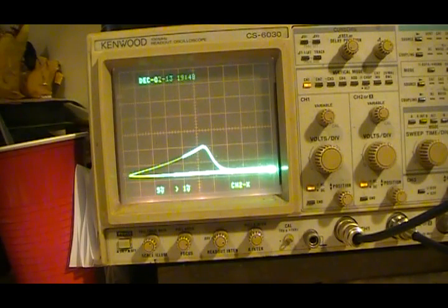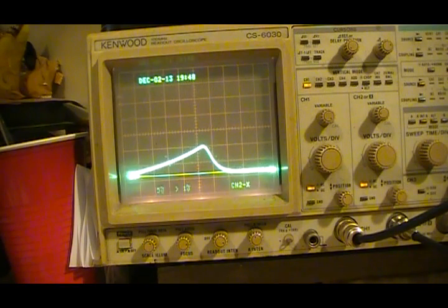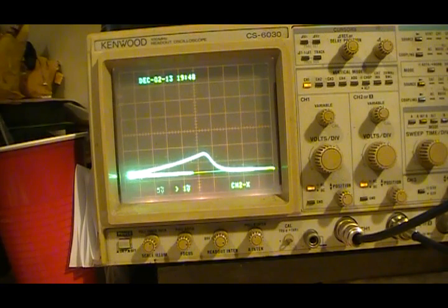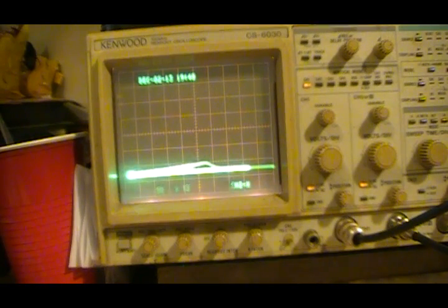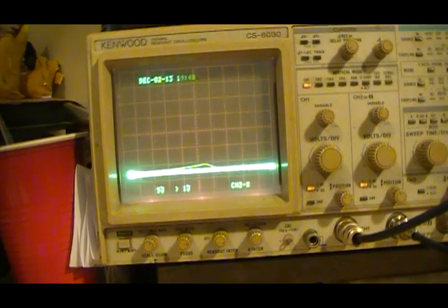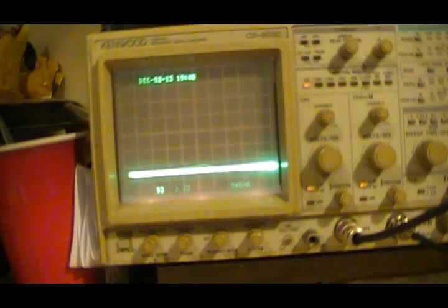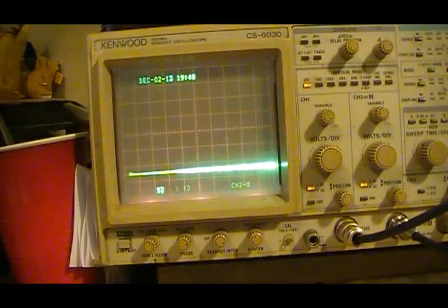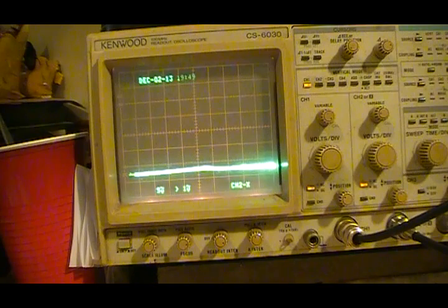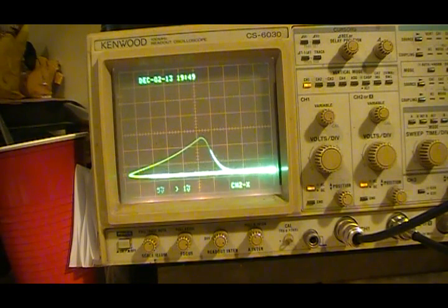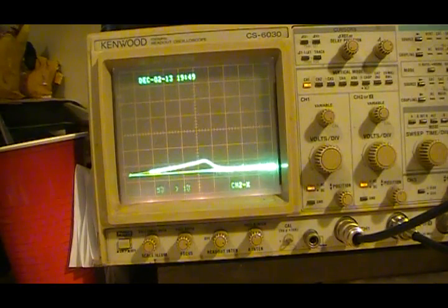There we go. Kind of lost a little bit of the blip here because I adjusted the generator up a little bit. But it's still giving me some troubles. Almost as though I think I'm losing a tube in this radio, as it gets hot. Could also be a resistor. Turn the radio back on, let her cool just a little bit. We appear to be having some issues with the tube.